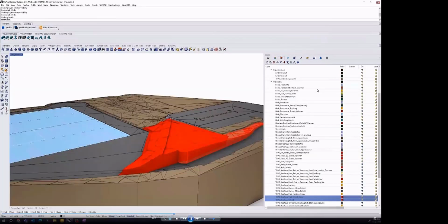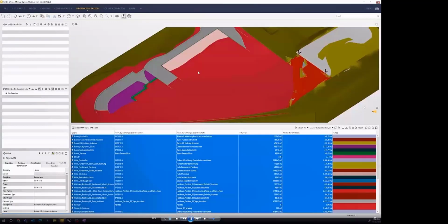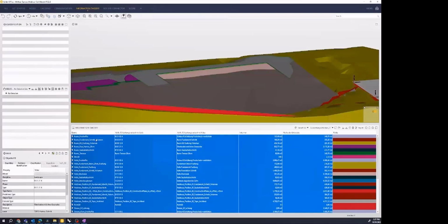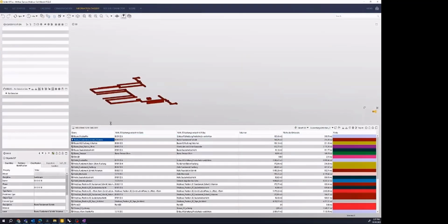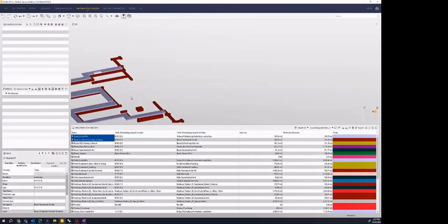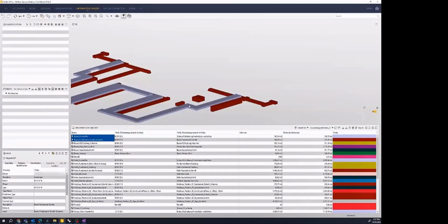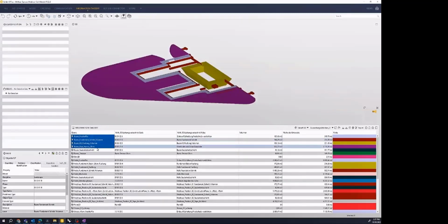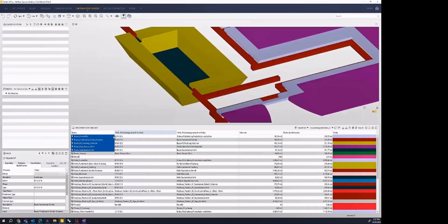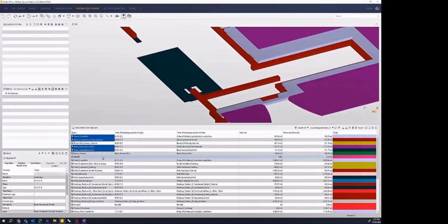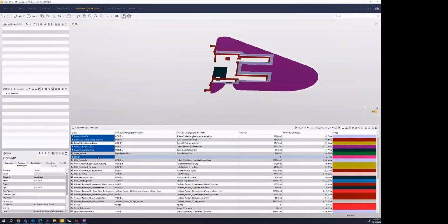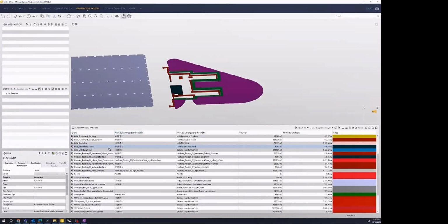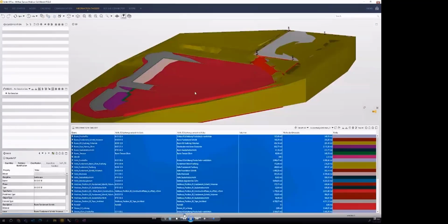So yeah, I don't know, this kind of model is maybe too crazy, but you can simply achieve it in Rhino. And here in Solibri, if you display and make a quantity takeoff, you can classify the volume of geometry with information from your classification, and this helps a lot to compare with bidding documentation. So this is one of the other use cases I was mentioning. And my discovery is that this VisualARQ IFC exporter works really, really well, so I highly recommend using it for your work scenario.